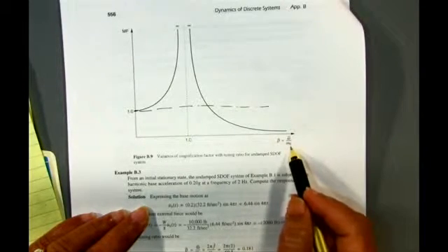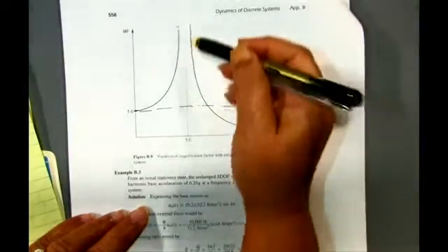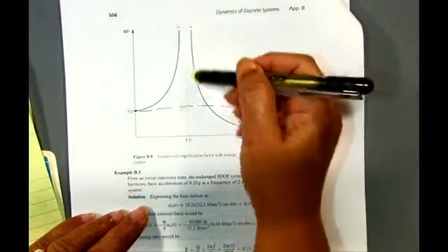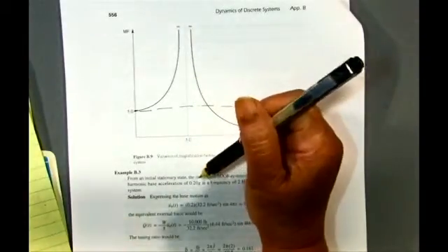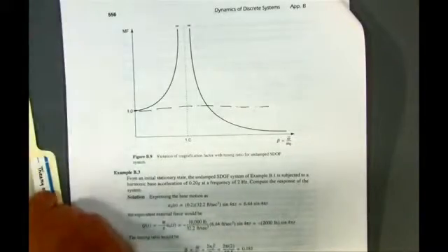It means that if the natural frequency is close to the forcing frequency, you can have large amplification, and in fact you can have resonance. Now, does it really happen in real structures and systems? Let me give you 2 examples.